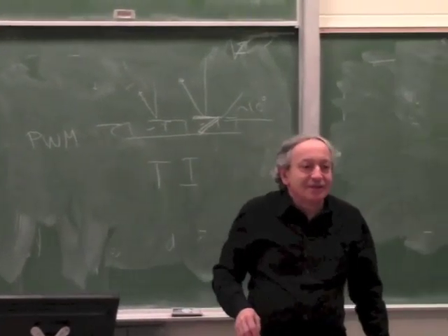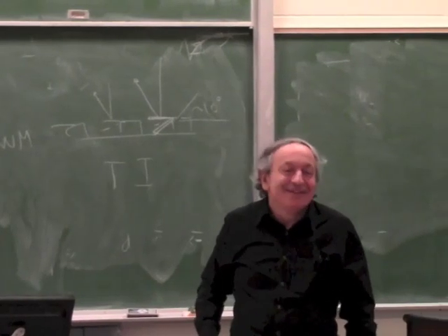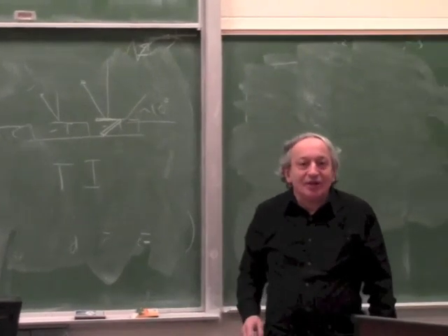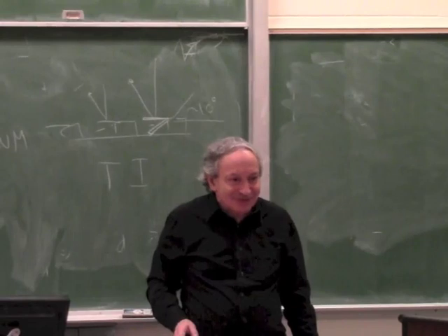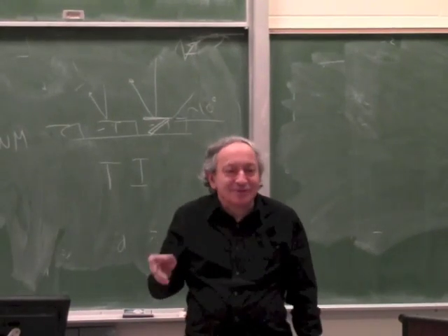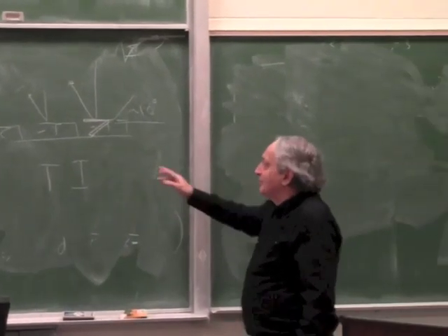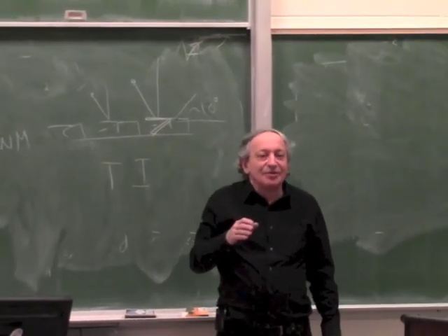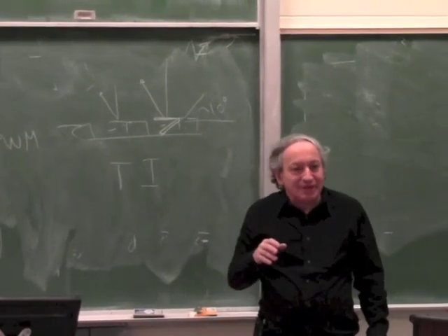Yes? How long do they last? A long time. Because aluminum has finite... Okay, so there's a lot of tricks here. Aluminum usually is a very bad material for fatigue, one of the worst. But if you make it very, very thin and with the right processing, it works. The interesting thing is it's not silicon, because the best thing to make these mirrors is silicon. But silicon cannot take a very big stress. So it actually turns out to be better to make them of aluminum.